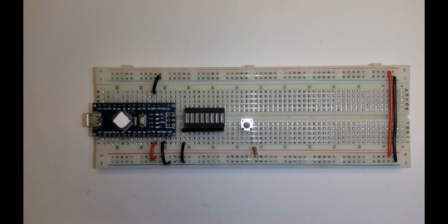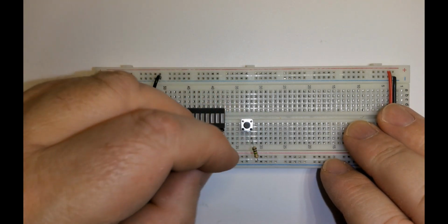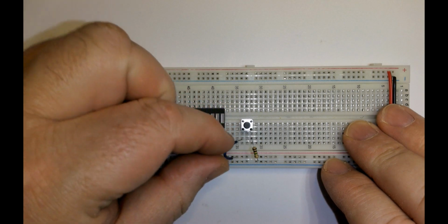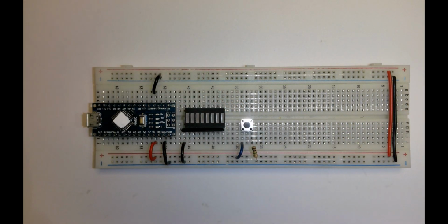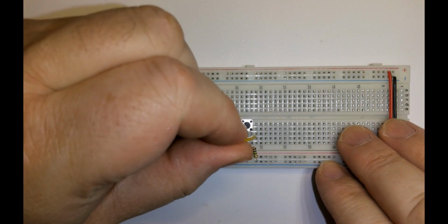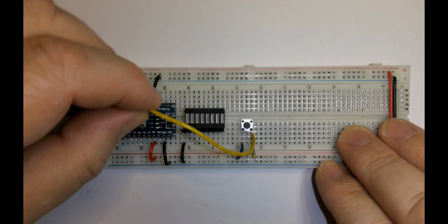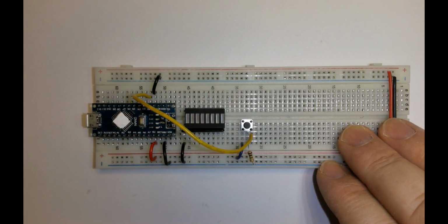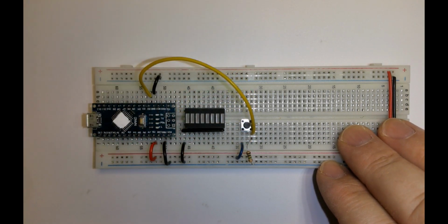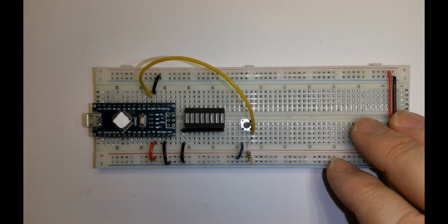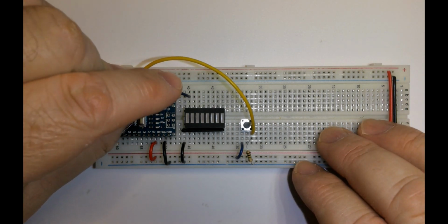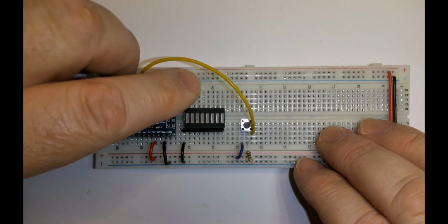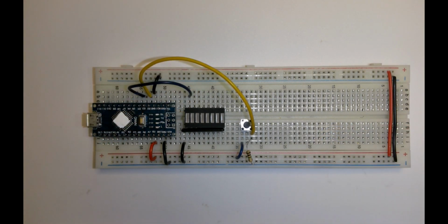Now the other side of the switch will go to positive, and that is my standard push button switch. The signal from the diagram comes from the top of the resistor, and then that goes into pin 2. So if I move it out of the way, you should see that. And the output from the LED, or output from pin 3, will go to the LED. Alright.